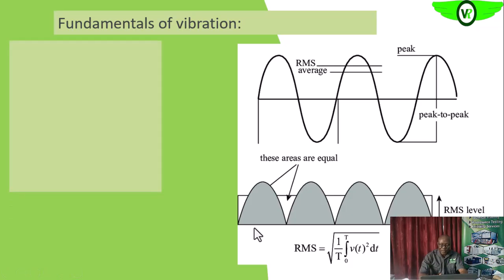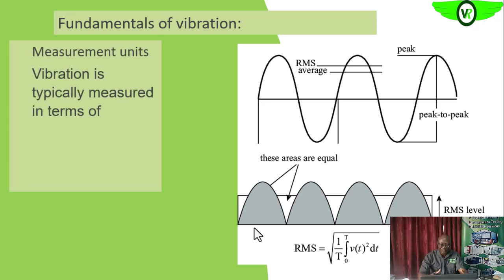So the probe, as you are collecting the information, the vibration measurement equipment will be giving a direct reading, either a root mean square value, amplitude in mils or millimeter, and then the peak to peak value also in millimeter. So this now becomes the measurement unit for our amplitude.